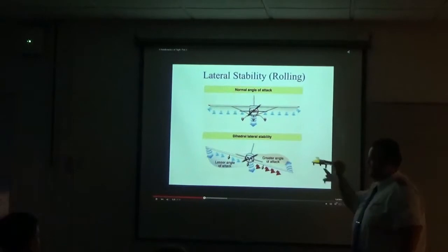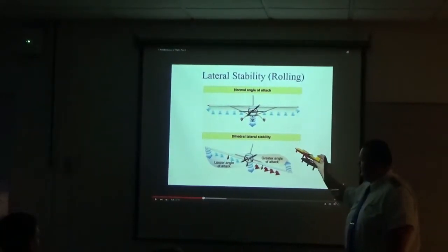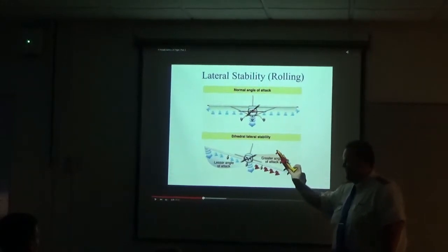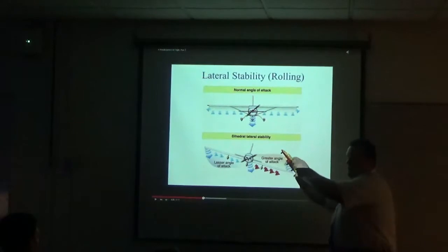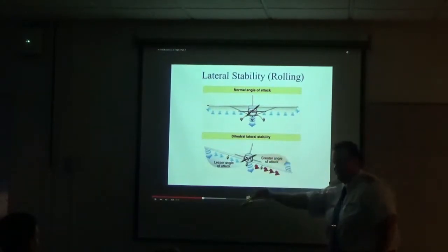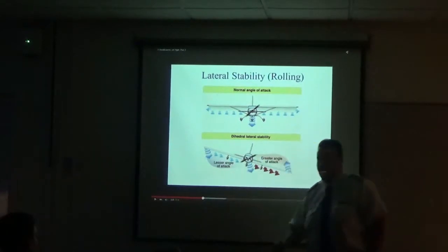In fact, an aft center of gravity is the most dangerous thing you can have because it causes you to have less controllability of the tail section, and sometimes it can be so heavy it can cause the aircraft to just constantly rotate up and put it into what's known as a tail stall. And because it just stays like this, there's no way you can force that nose down to recover. It's just going to stay there because it's just so heavy back there, and boom, it crashes.